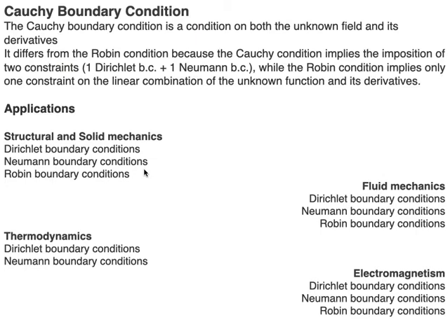As stated in the section dedicated to Neumann boundary conditions, the homogeneous condition is naturally satisfied, so free boundaries do not need to be modeled explicitly in Neumann boundary conditions. If you look at a Robin boundary condition, this is not a major kind, but it is used to model the mechanical impedance of a structure, that is, how it resists motion when subjected to a harmonic load.